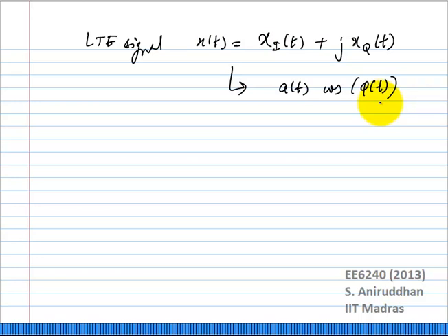What do you think the bandwidths of the amplitude and phase modulated signals will look like in the polar domain compared to the bandwidths of the Xi and Xq? Now this will really be a function of what kind of modulation you use, as well as the details of that modulation.